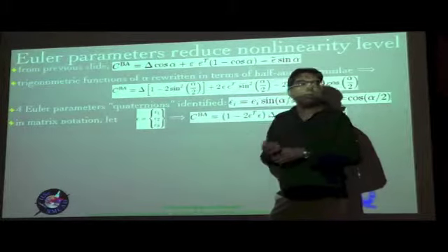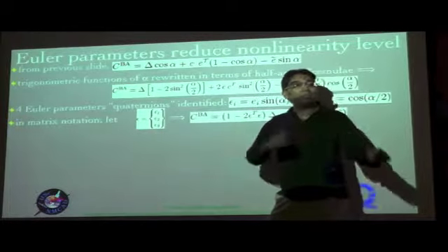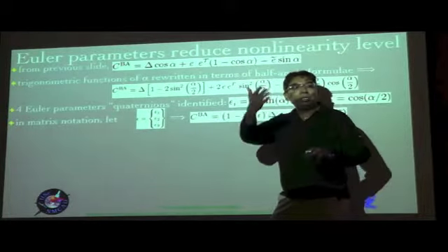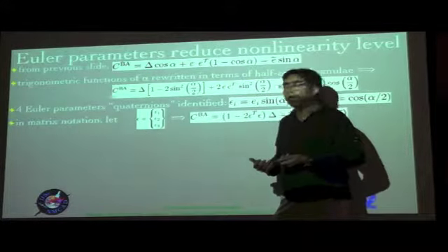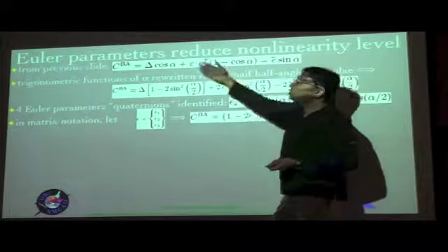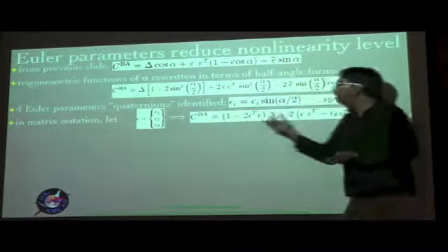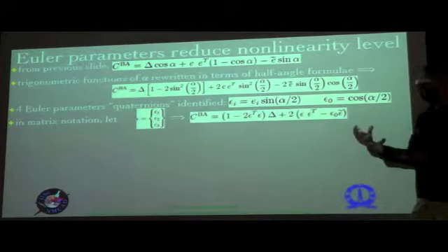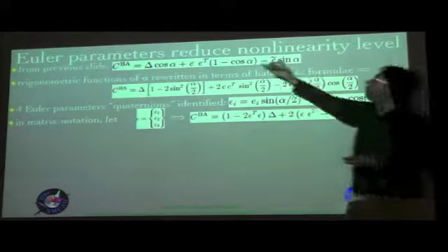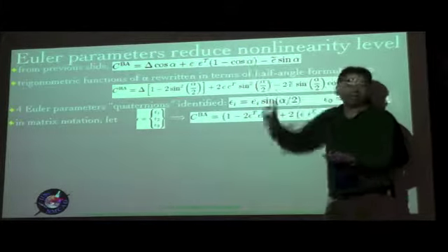But we are not interested in such a situation, and in particular for our own situation we want to deal with rigid body like rotations of the cross section to be as large as they need to be. In such situations it's not possible to curtail a power series, and so a representation like this will make the nonlinear problem a little more tractable compared to a nonlinear problem involving an expression like this.